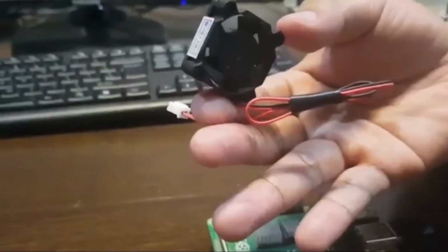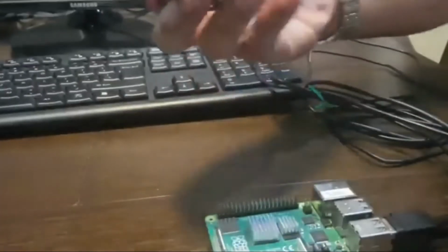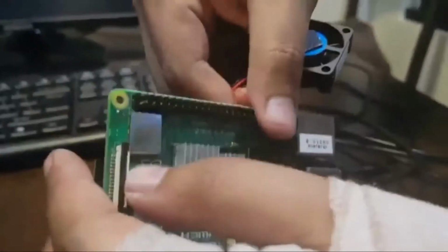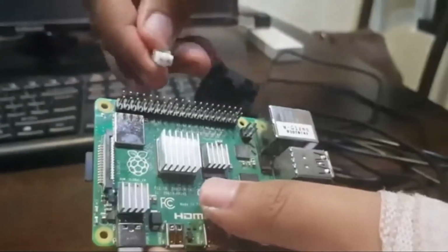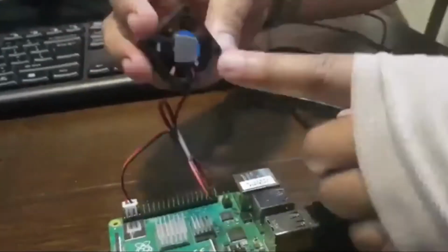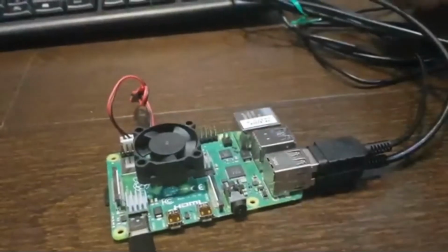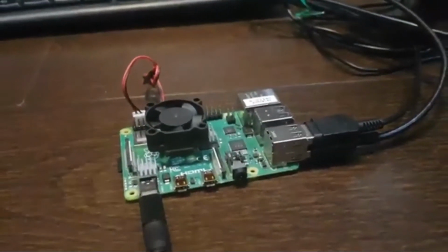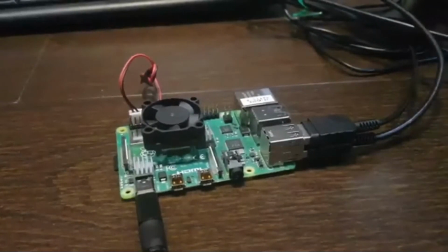We added the cooling fan on the Pi for caution. Although the appropriate heatsinks are already there, the cooling fan helps avoid overheating. We connect the red female connector to the 5V pin and the black male connector to the GND, the ground pin inside it. To keep it from moving, we place double-sided tape under the fan before placing it on top of the processor.